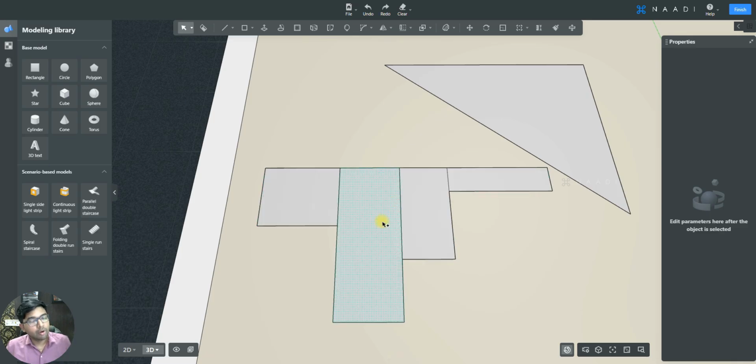making that into one single geometry. Or you have your erase tool here. Just click it, and now using your erase tool, select the line. That specific line will be deleted. Can you see here? But your SketchUp eraser tool has an intuitive way of erasing a line, right? You could just drag it across a single or multiple lines so that they will be deleted, correct? That is also feasible. For that, you have to hold shift on your keyboard. And now if you just left click and drag across multiple lines, can you see? All those selected lines will be highlighted. And now if you just leave your cursor, all the selected lines will be deleted in a single instance. So this is what your eraser tool is, using which you can edit a 2D geometry.